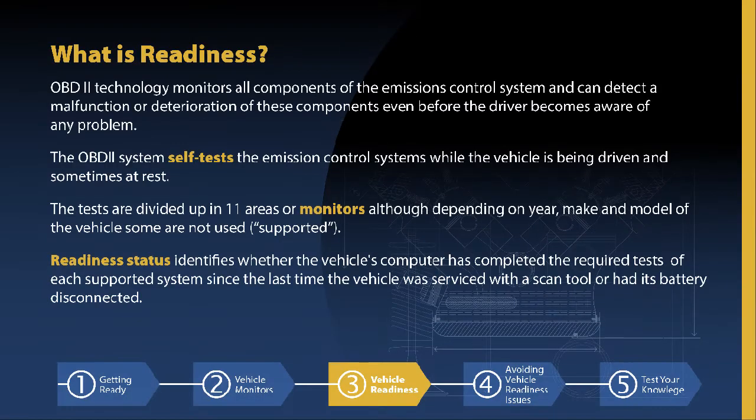Now that we understand what monitors are and how they work, we can talk about readiness. The readiness test is essential in determining a car's health, as it verifies if the car has completed its self-tests. So when you plug your scan tool in the car, you are checking to see if all the supported systems are ready, meaning the car has checked the systems. If the vehicle reports that there are more than 2 systems that are not ready for testing, you have to reject the car for readiness issues.